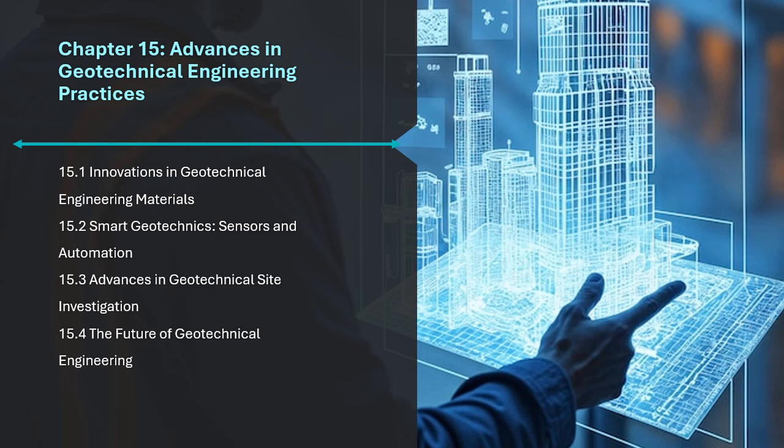Accelerometers. These sensors detect and measure acceleration or ground motion. Accelerometers are commonly used to monitor seismic activity or the impact of vibrations during construction, providing valuable information about dynamic soil behavior and the effects of earthquakes or machinery-induced vibrations.